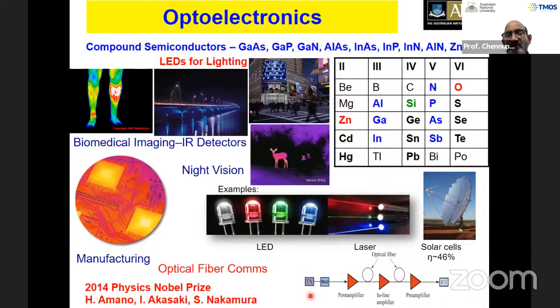Again, we make use of these indium gallium arsenide phosphide materials, both for sources and detectors, because that's where the small amount of absorption and dispersion takes place at 1.3 and 1.55 micron wavelengths. These materials have the appropriate band gaps and are able to provide the light emission and light absorption characteristics.